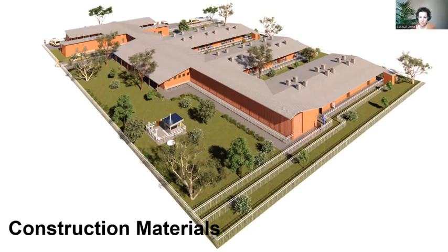As already mentioned, the building ventilation should be included in a broader and holistic design strategy that encompasses the building envelope, the construction material, the structural elements. Indeed, the presented proposal envisioned a wall system that is critical to the effectiveness of the natural ventilation and thermal comfort proposed. Such walls are proposed to be made of high massive material, like raw earth blocks. Those can be stabilized with 7-8% of cement to close all the micro voids in the block and develop waterproofing features to increase durability and decrease the maintenance in future.